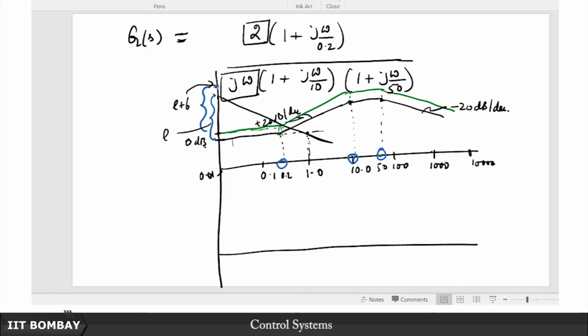So, and you are done. Now you draw this Bode plot all the way down till here. At this break frequency, you see the green line had a slope of plus 20 dB per decade, so you will have a slope of 0, and you go on like this until at this point you see the green line had a slope of 0 dB per decade.